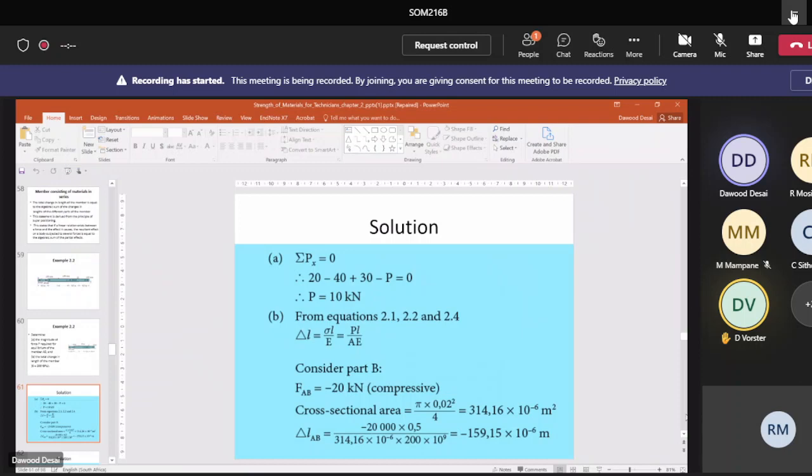Right. There's another type of question now, which is a class B type of problem, where you got end loads. Okay, there's the end load. This is a much easier one now. The rule says now that the force along the complete length or any part or any segment of this member is equal to P. That means P acts at AB, it acts at BC, it acts at CD. I'm going to put a D here. They left out the D.